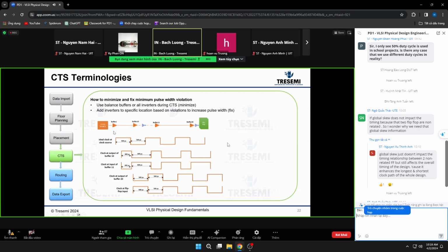So let's say that for each of the buffers here, the rise and the fall are unequal. Each time it goes through the rise, it will eat up 10 picoseconds. So by the time it goes through the first buffer, the rise is going to be 490. Each buffer eats up 10, so you only have 400 picoseconds after the 10th buffer, right?